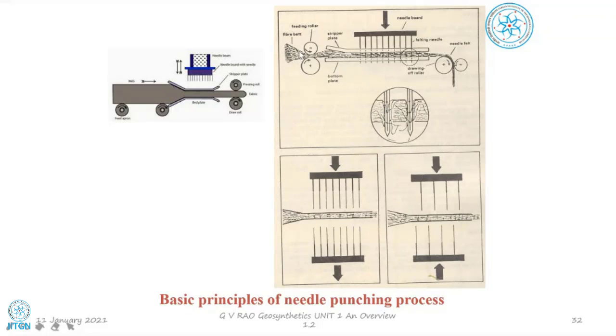The fibers are all horizontal. Initially, they are compressed by feeders, the actual feeding roller now. They were loose and slowly they become thin. And out comes the non-woven geotextile. Non-woven needle punch geotextile is going to come out by the end of the process now.